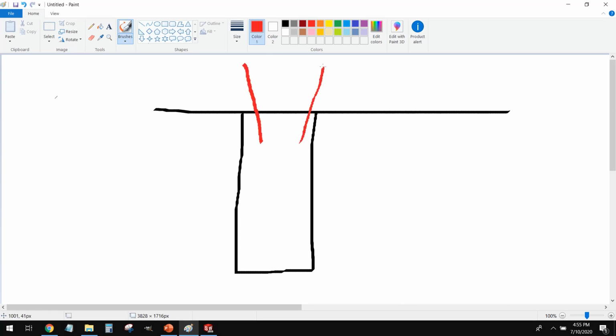And a tap is just essentially a screw that has flutes cut into it to cut chips. But that has a slight taper, and that's to aid the cutting process. So when it cuts threads, it's not going to cut all the way to the bottom with a standard tap. It's going to cut it 3/4 to 80% of the way. And that's fine for most holes.